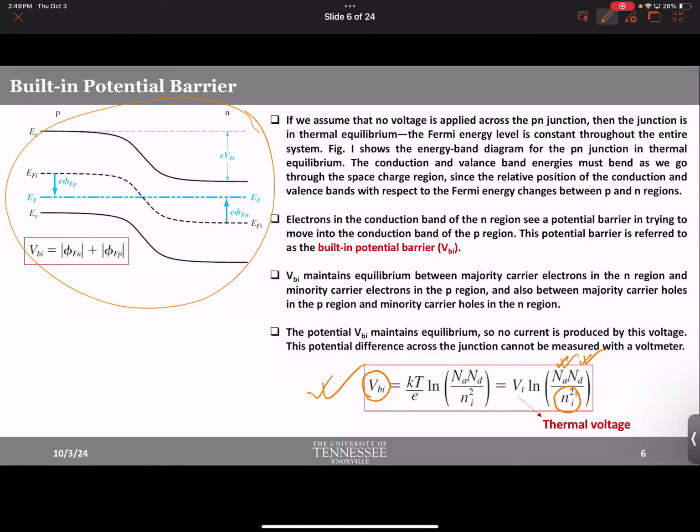So for silicon, there is a band gap. For germanium, there is a different band gap. So you have started working with diodes already. Do you know that there is a turn-on voltage for a diode? Minimum. For silicon, it's around 0.7, right? For other materials, it will be different. Why is it always that number?